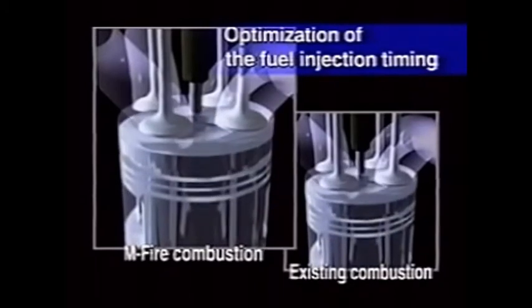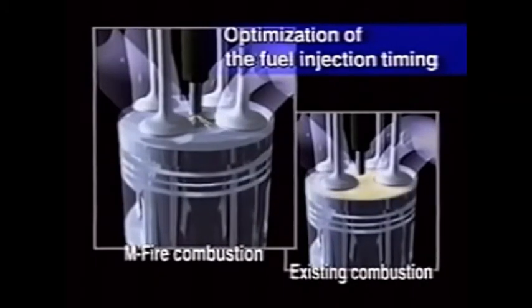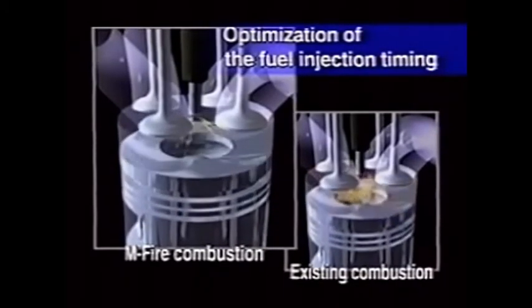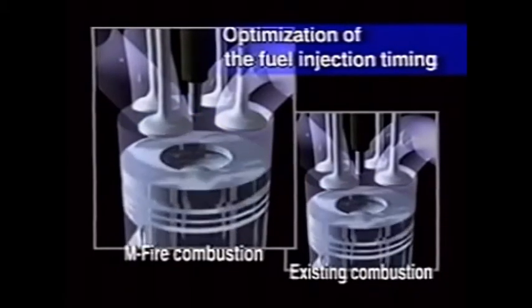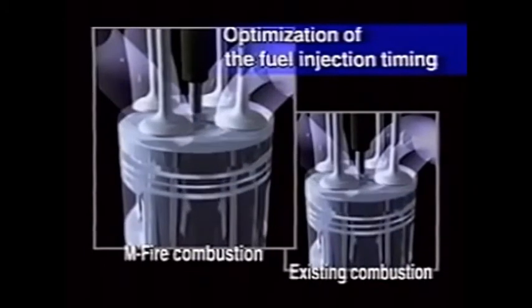Moreover, the fuel injection timing has been optimized by considerably retarding the injection of fuel compared with existing diesel engines. This completely new approach moderates the combustion process, so that combustion noise and engine vibration are greatly reduced.